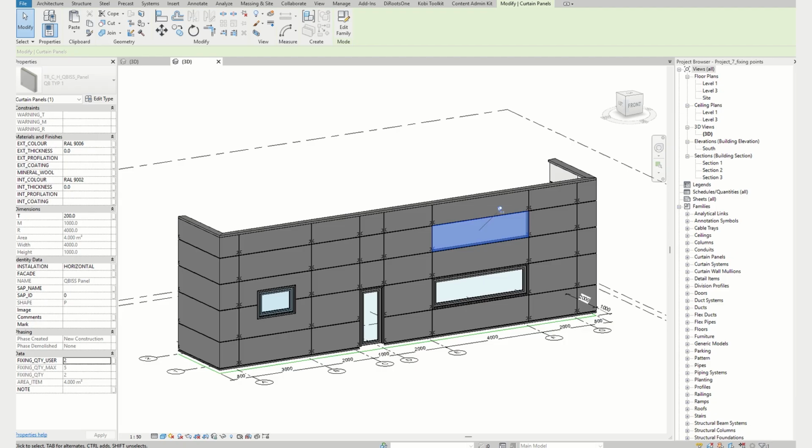What else do we get from static calculation? Static calculation checks if panel with chosen thickness, steel sheet thickness, profilation, and mineral wool core will carry load on required span. Panel thickness, steel sheet thickness, and profilation is usually same for all panels. Only mineral wool data sometimes varies. For bigger spans and corner area, sometimes wool with higher strength is required. Usually we have power T. For higher strength, we have power S.